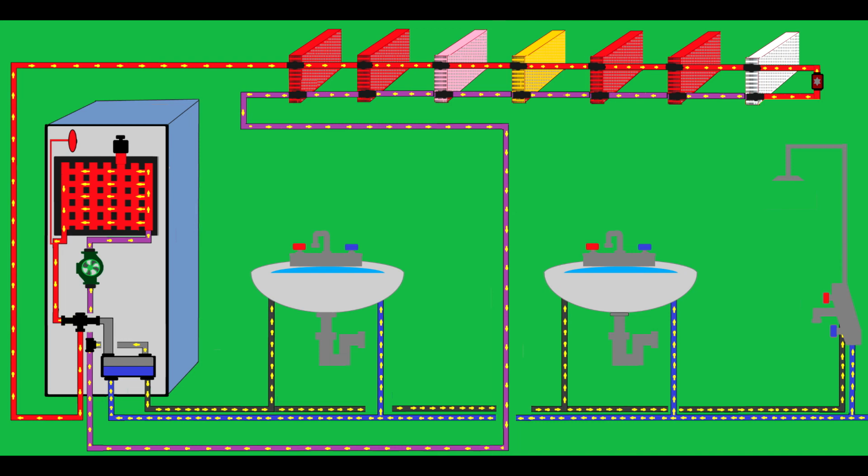Many people do not clean the installation inside. They're not flushing the installation. They think this is a joke. But a lot of debris and sediment will sit on the pipes, restricting the flow, because the pipe diameter will shrink more and more, and it will reach the point where you will not have enough circulation, and then the boiler will overheat, the radiators will be clogged with dirt, and you will waste more money on energy.